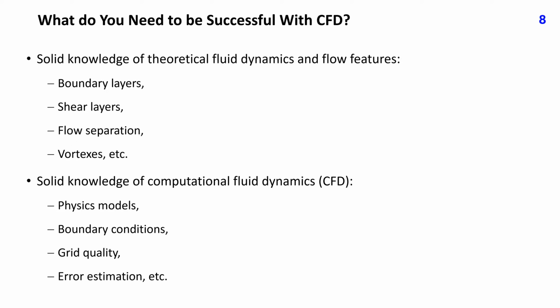You should have a solid knowledge of theoretical fluid dynamics and flow features like boundary layers, shear layers, flow separation, vortex generation, shedding, etc. The more you know about the flow to be simulated, the better you can adapt the grid design and other simulation parameters to the expected flow features and obtain a good solution without many trials.